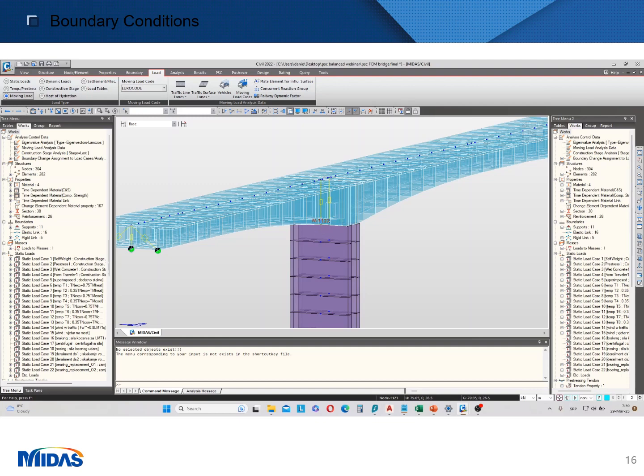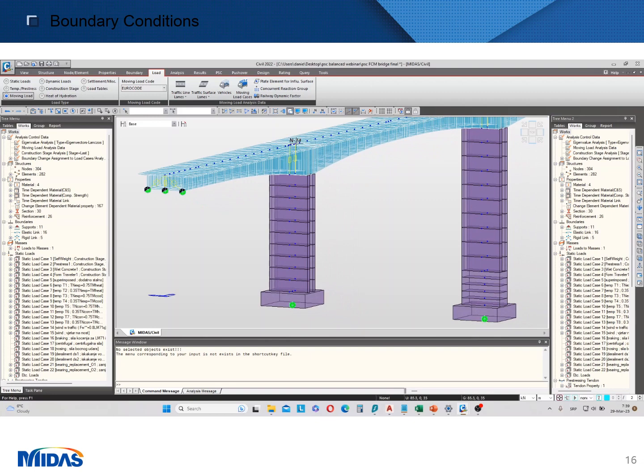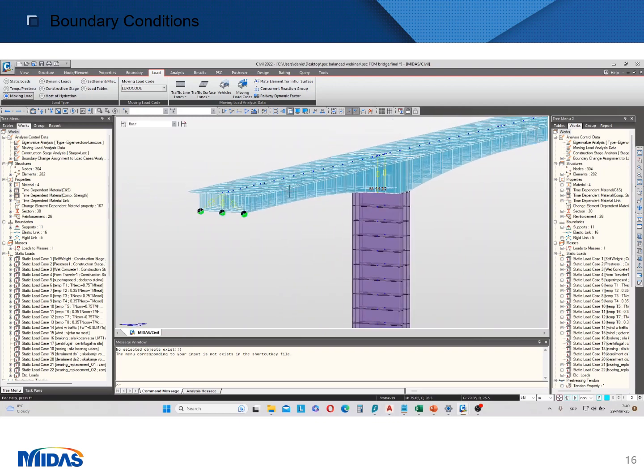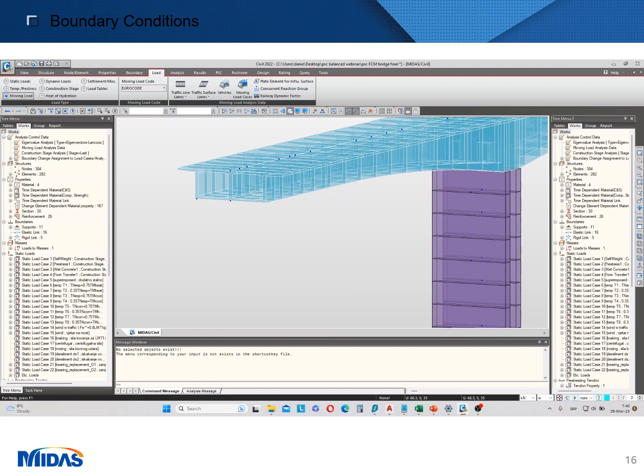Okay, so you see we have elastic links type rigid between superstructure and piers. So you have maybe noticed that there are two types of links that can be rigid. We have rigid links that only connect elements, and the elastic links type rigid are different because they can actually show you forces they are transferring or deformations. So we use them also to connect parts of the structure, and for example here we used it to connect superstructure end to the positions for the pot bearings.